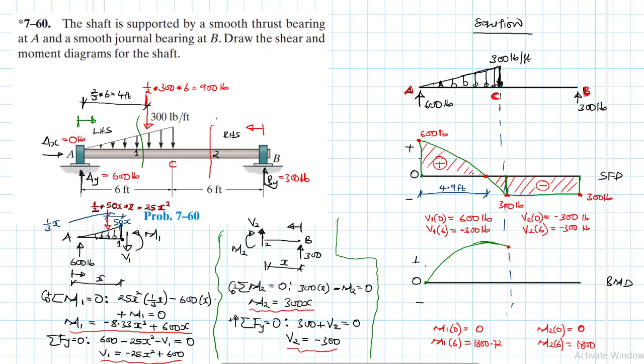The moment is equal to 0 when x is equal to 0 at B, and then the moment is equal to 1800 when x is equal to 6 feet from B towards C. So this is a straight line, and it will just go and meet that point there. Of course, there are minor differences. We've seen 0.72 and we don't have any point there. It's because of rounding off. That's the reason why we have these minor differences.